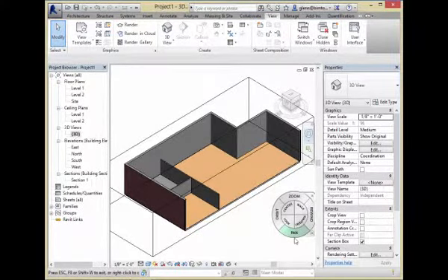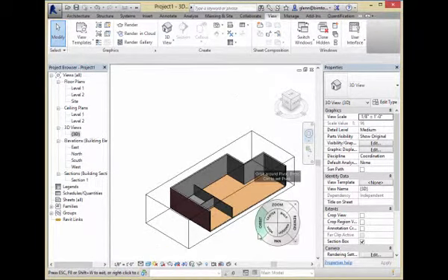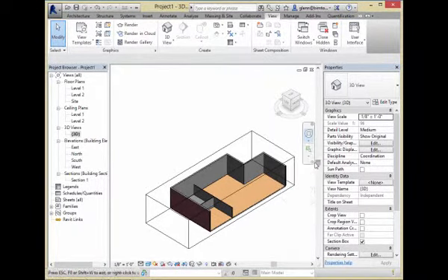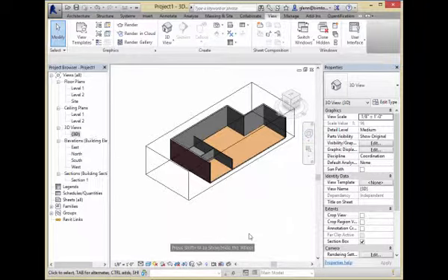Now we have this section box hanging around. The section box cuts away the model. The cropping just cuts away how things are presented on the sheet. That's the way to think about it. Does the notion of using the section box make sense? Is that part okay? Okay, so then the cropping issue is, although this is sectioned this way, it's not necessarily cropped. I still would like to crop it so it's going to fit on a sheet.